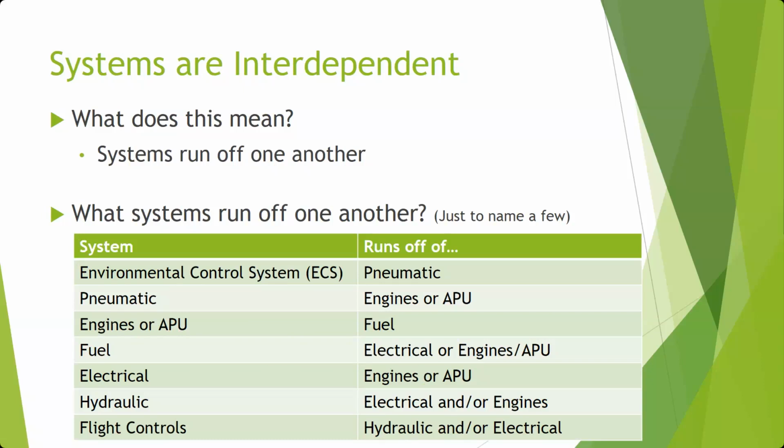What about indication? What if it's just a bad gauge? Is it the gauge, or is it the wiring going to the gauge, or is it the sensor that's picking up the pressure to feed to that wire to that gauge? Right. This develops something as we're thinking through these items. We need to follow what's called the path of influence. When you take a troubleshooting class, we'll discuss that in more detail.